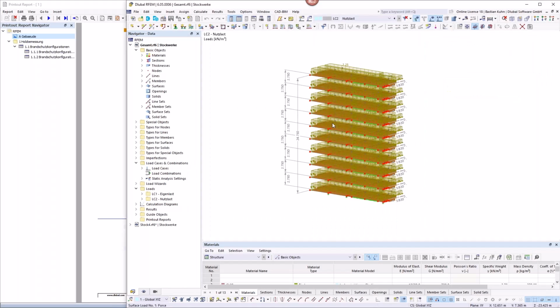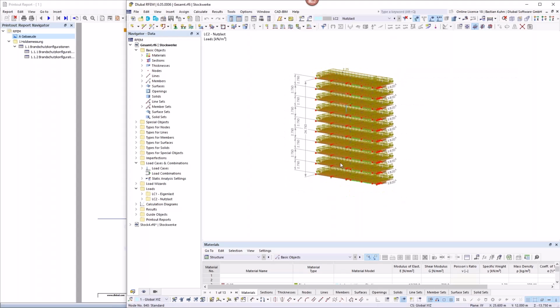As I said, I want to calculate that in a 2D structure, but with 3D effects. Therefore, just to give you an imagination of the structure, I copied the top stories 4 to 13 in a separate position, so that I make a simplified load case there for the self weight, 4 kilonewton per square meter, and the live load, 2.25 kilonewton per square meter in each story.